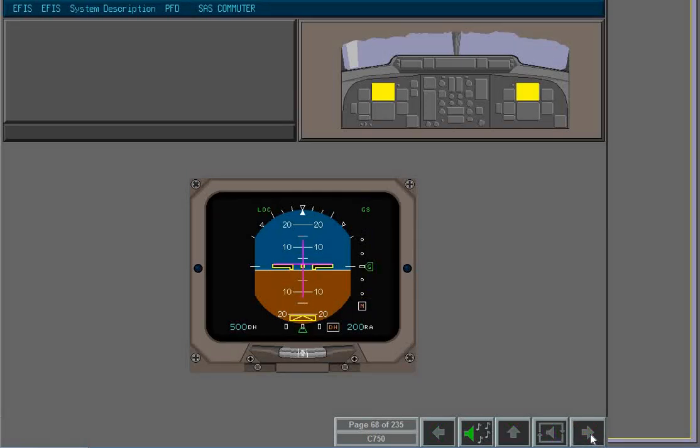The glide slope scale and pointer flash amber in the event of excessive glide slope deviation. The glide slope indication returns to normal when the vertical path returns to within the allowable excessive deviation limits.